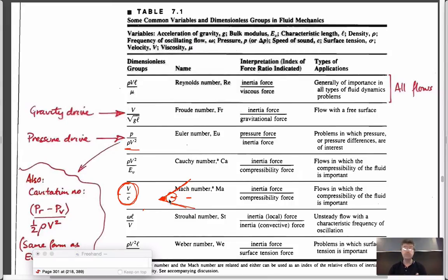The analog, I guess, would be on a plan view of a ship traveling through water. It's trying to push a bow wave ahead. The bow wave travels at a certain rate, the celerity wave speed in our particular case. If you're going faster than that bow wave, then you end up with a wake because it can't physically get away from you faster than you're traveling. And so to be able to push the ship through the water, you have to actually almost surmount that bow wave to be able to move forward. And so you have to expend extra energy to do that.